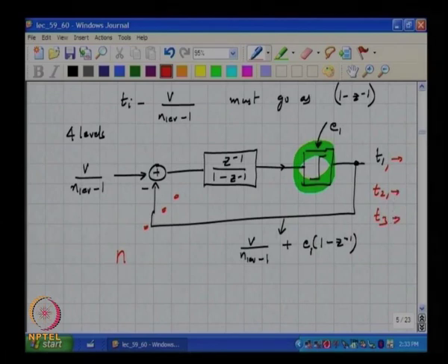of harmonics, at least in principle, okay, because each one of these waveforms is a linear representation of the input. Unfortunately, the in-band quantization noise will rise significantly because it is now as if you are operating the whole multi-bit, I mean you have converted a multi-bit delta sigma modulator into a single bit one.